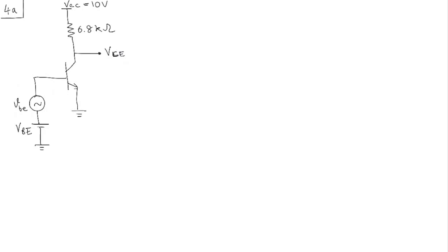of the transistor, and the relation that tells us that the collector current is equal to Is times e to the power VBE divided by VT. We've been given the value of Is in the problem, and VT is always equal to, or you can assume it to be, 25 millivolts. Okay, so basically what we want to do is calculate IC and then calculate VBE using this equation. So what is the value of IC here?